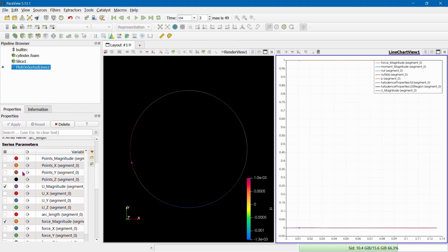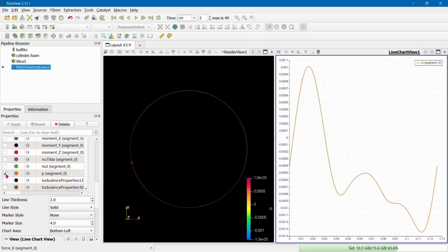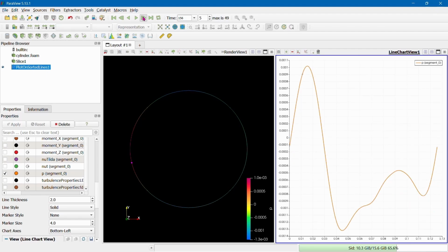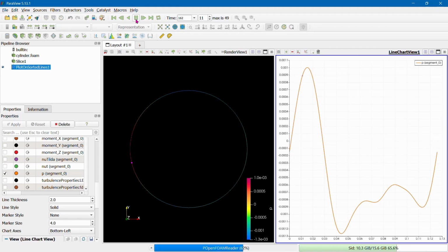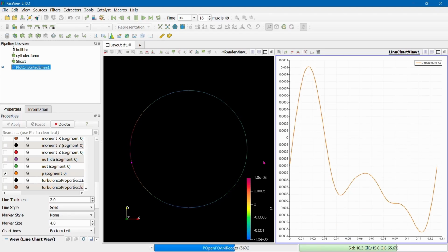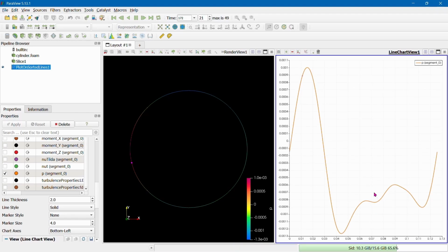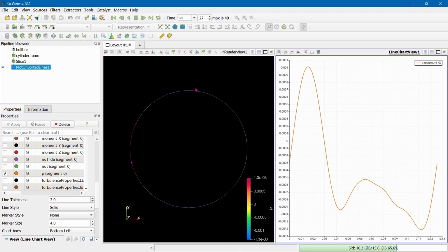Even with the plot, if we are only interested in the pressure, I can just select the pressure right here and you will see that we now have pressure data on top of my entire cylinder, and this is time accurate in the sense that as the time aspect of it increases, we will see a particular spike of the pressure somewhere around right here, and the pressure essentially keeps increasing and decreasing on the top and bottom portions of my particular cylinder.